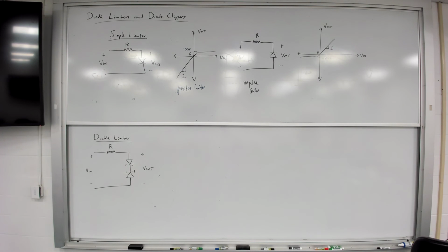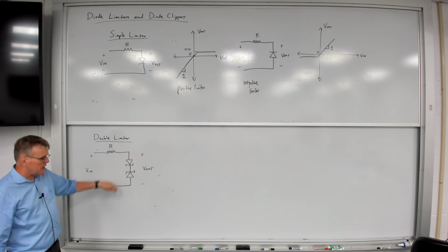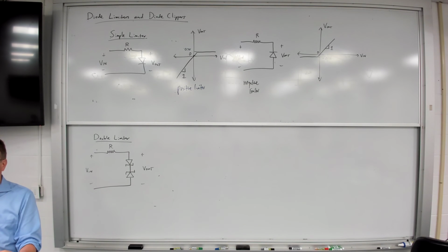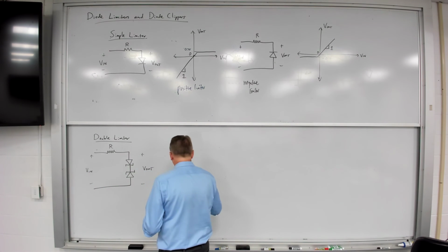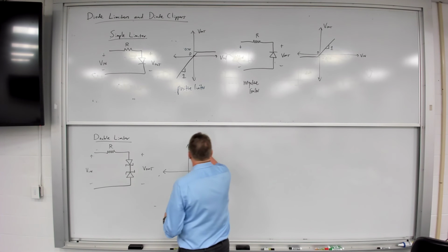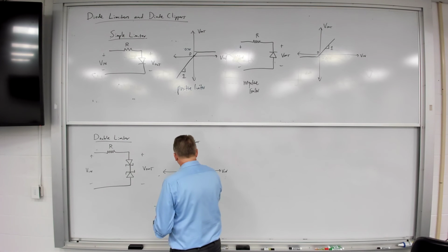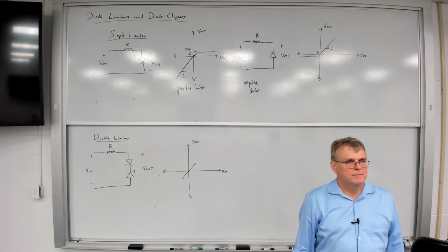You look at that and you kind of wonder, how's this supposed to work? Well, if you think about this circuit, in order for current to flow through these two diodes, one of them has to be in reverse breakdown and one has to be forward biased. And you can forward bias a Zener diode. It works like any other PN diode if it's forward biased. So if I sketch Vout versus Vin, at low voltages Vout is just equal to Vin. Both diodes are off.